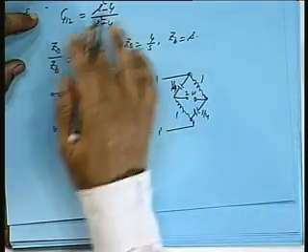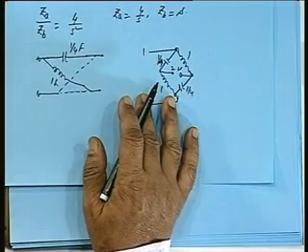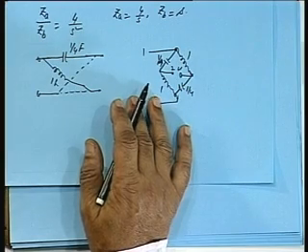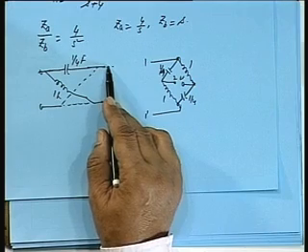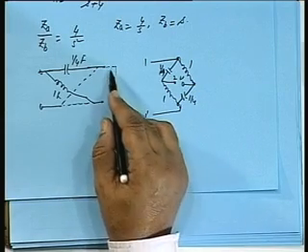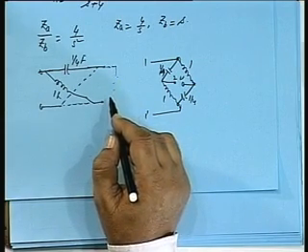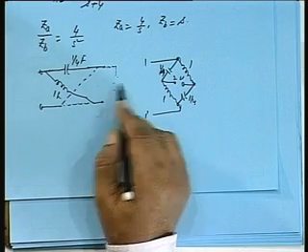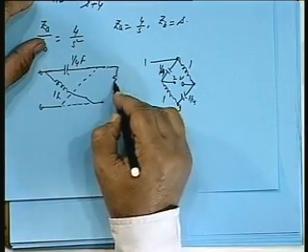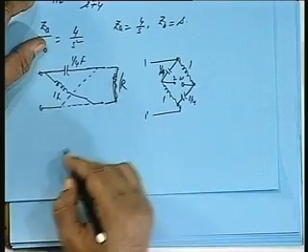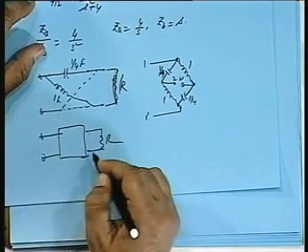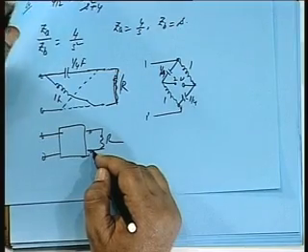Now, this is the basic background that I have given for 2-port lattice synthesis. Now, normally the networks will not be necessarily terminated by infinite impedance, they can be terminated by a fixed impedance. Sometimes they are terminated by fixed impedance. So, if they are terminated by a fixed impedance, what is the relationship between output and input? That is, for a terminated network which is terminated by a constant resistance R, not in this example, you have a 2-port network, and if we have a terminating resistance R, then what will be the relationship between input and output? Okay.